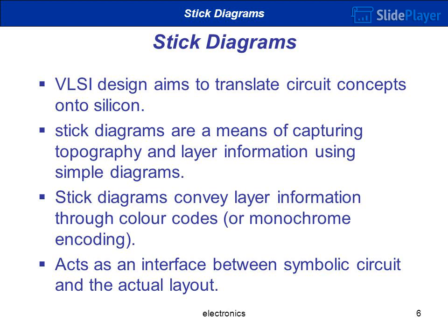VLSI design aims to translate circuit concepts onto silicon. Stick diagrams are a means of capturing topography and layer information using simple diagrams. Stick diagrams convey layer information through color codes or monochrome encoding. They act as an interface between the symbolic circuit and the actual layout.